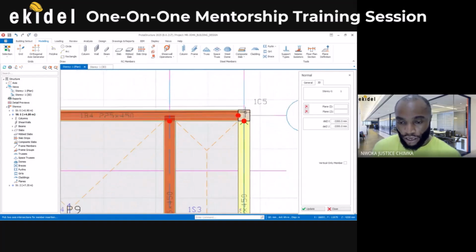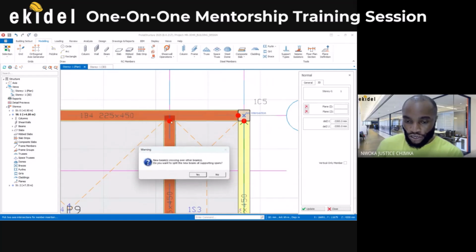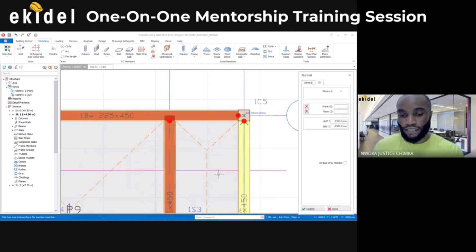I'll come again here and click here. They will ask me a question to split, because there is a beam already showing here. I'll say no, because if you say yes, it will divide the beam at this point, which is not nice. So I'll just say no, don't split. Just click on no.